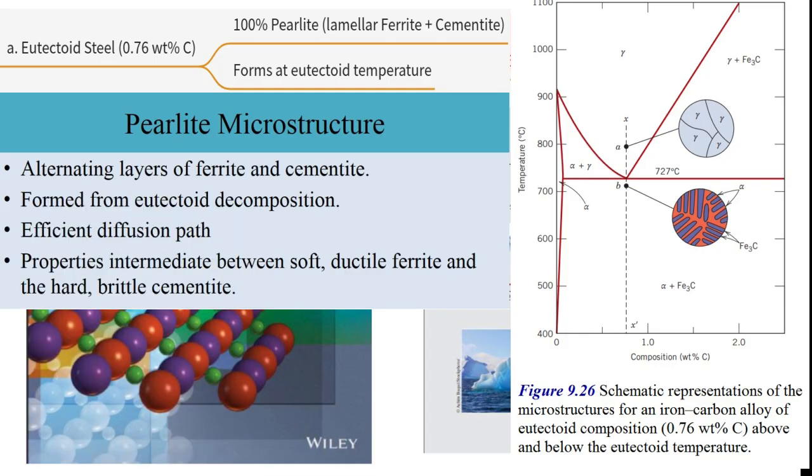It comes down to diffusion. Remember, you have austenite with 0.76% C transforming into ferrite with only 0.022% C, and cementite with a whopping 6.70% C. Big difference in carbon concentration. Huge difference. Carbon atoms have to move. They have to diffuse out of the regions becoming ferrite and into the regions becoming cementite.